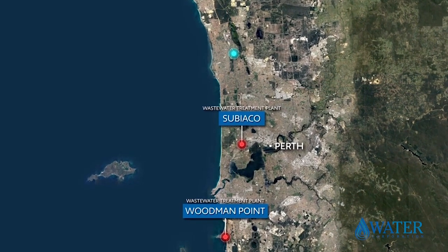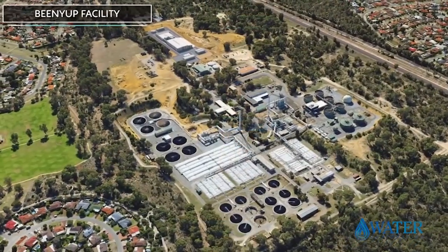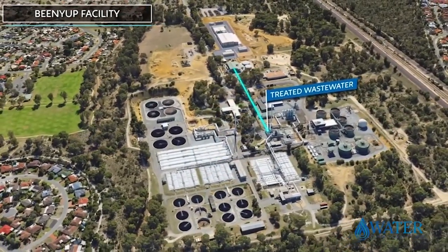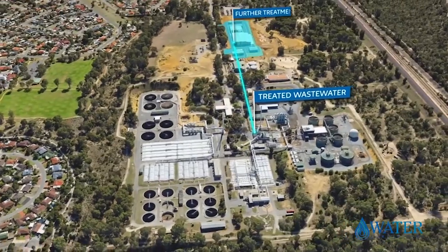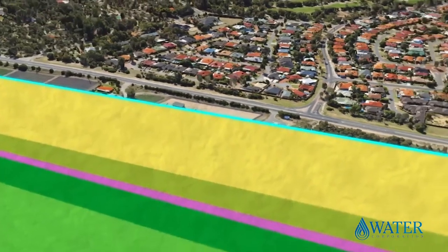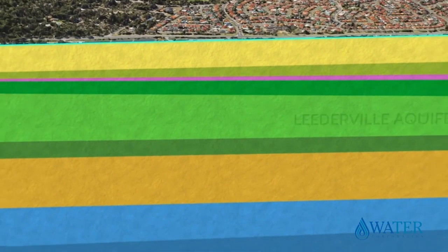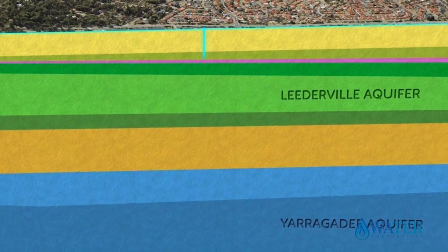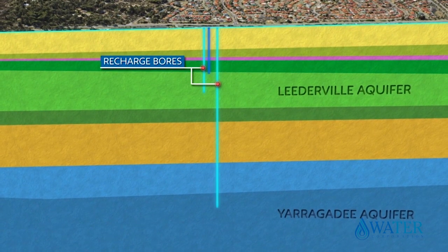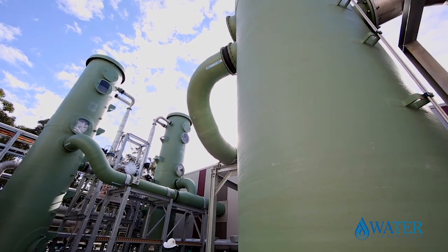Australia's first full-scale groundwater replenishment scheme in Perth, Western Australia, creates a new climate-independent water source and increases water recycling. The scheme uses an advanced water recycling plant to treat secondary treated wastewater to drinking quality standards before it is recharged into deep underground aquifers and stored for future treatment and supply to the drinking water network. This recharge supply is then able to be extracted on a one-to-one basis and contribute to Perth's drinking water supply.